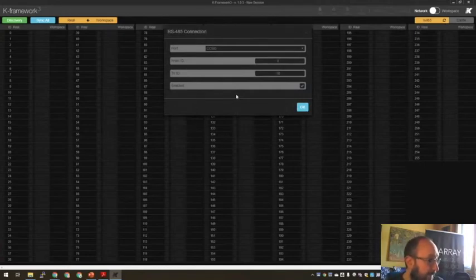And then Dante. We use our Dante devices, the Dante, to bring audio signal and also the remote control over the RS485. So basically, we are tunneling the serial over Dante. So we call it Dante because of that. We suggest to have the Dante controller installed on the computer so that anyway you can recognize all the Dante devices also for the audio part.